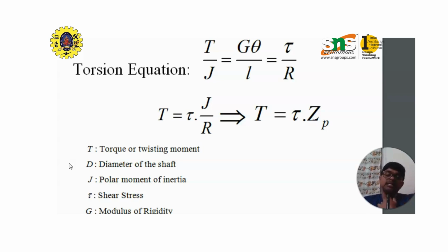That radius can be determined as half of the given shaft diameter, and we need to say whether it is a solid shaft or a hollow shaft, according to the given problem. So here T represents the twisting moment, or otherwise the torque, and J represents the angular polar moment of inertia, wherever the rotational load has been acted.